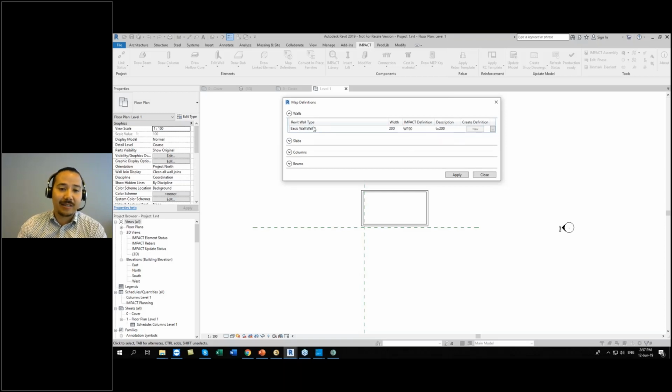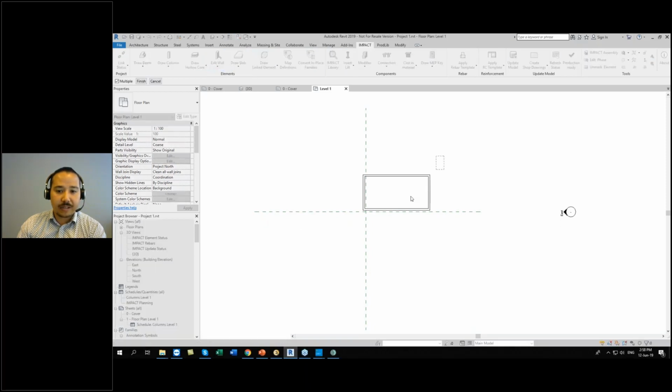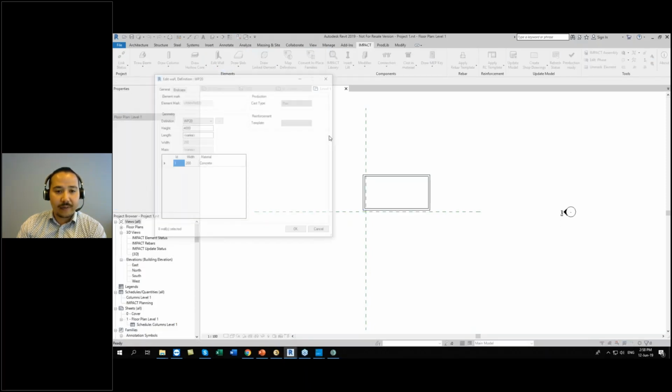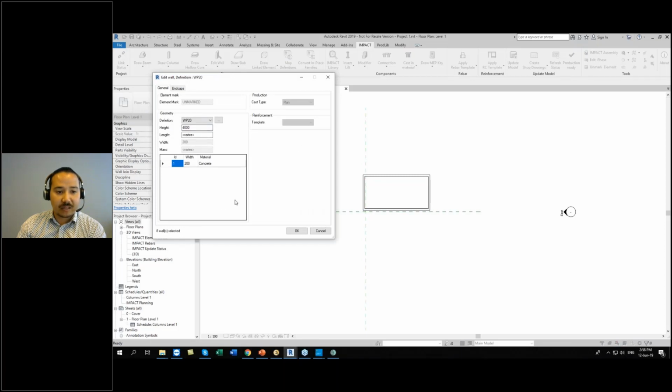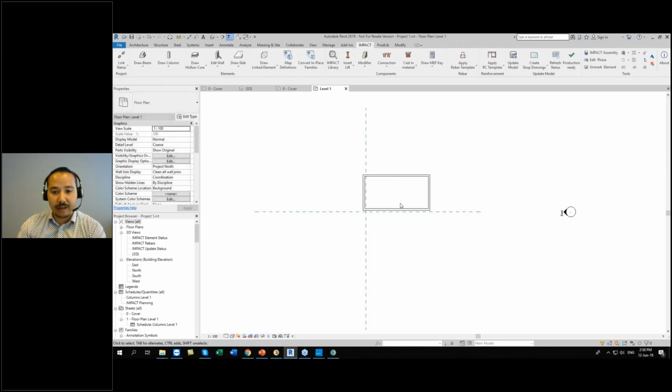It's basically the same thing we do here with the Revit type or category into an impact definition. So we're mapping one piece of information over to another so we can work with it. Actually the same thing as IFC. So now the elements are mapped, and we have the possibility to select all the walls. I'll press OK here to make sure that the lifts and bracings and stuff like that are added.